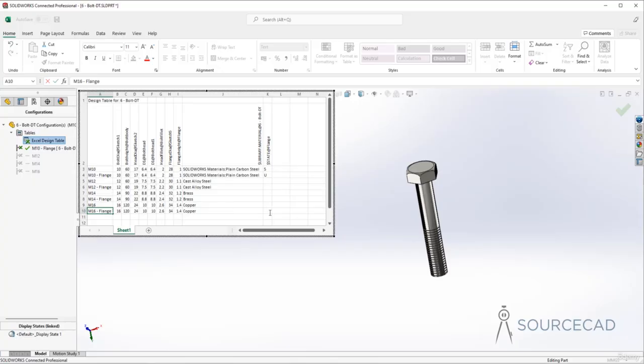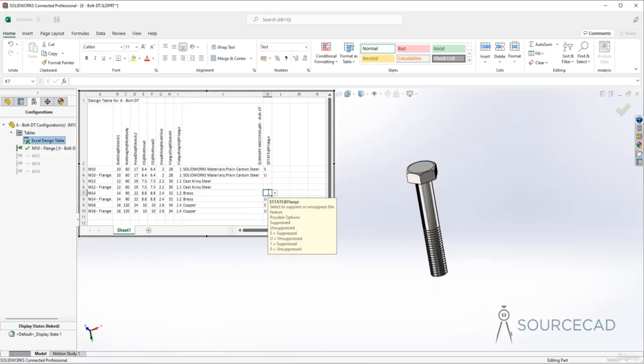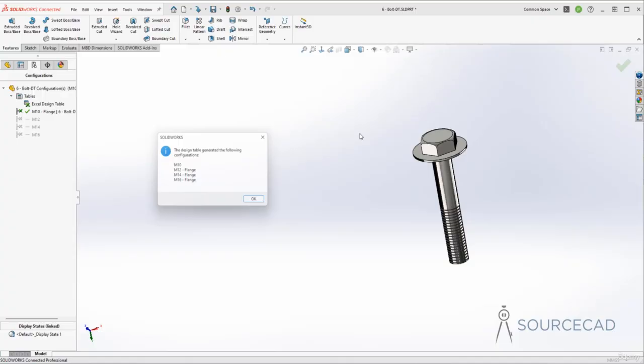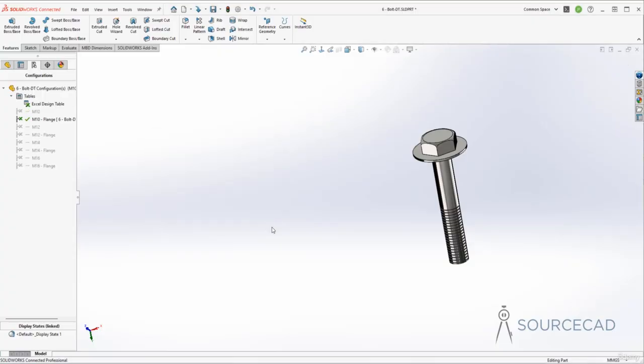All right. Now, wherever we have the flanges, I'll make sure that it is unsuppressed. And for the second one, it should be suppressed. This one has no flange, so it should be suppressed. Once again, unsuppressed and suppressed, unsuppressed, and this should be suppressed. So we've added all these suppression states. Now with all these changes, let's just click outside, and we have several new states added here, the configuration. So click OK, and here we are. Now, before actually checking it, let's just save it.